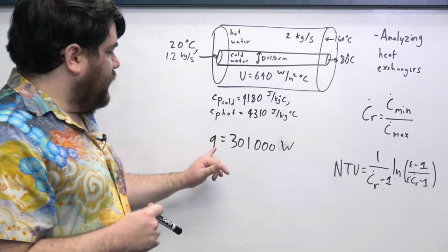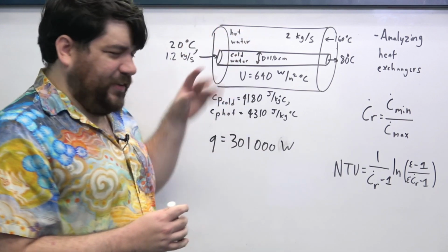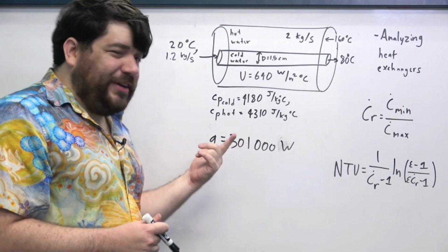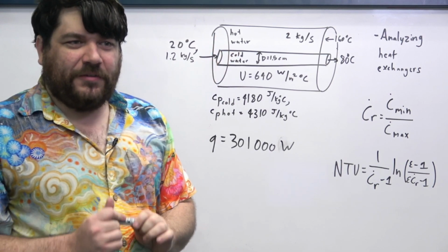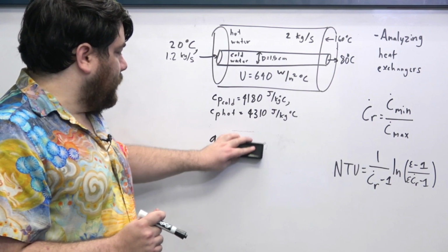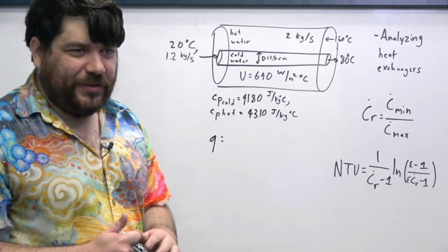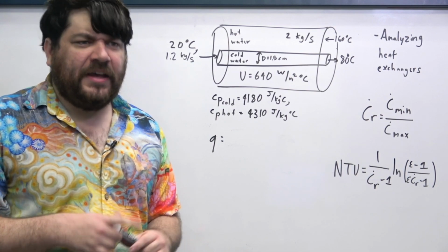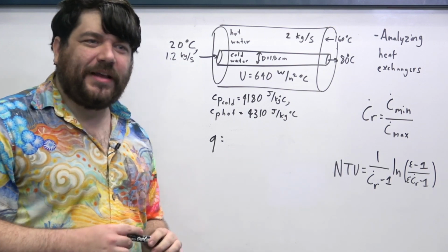Okay, can we use this information to find something else about the state of this heat exchanger? And the answer is yes, because we can use that same golden rule to try to figure out the temperature of the hot liquid at the outlet. Remember that the equation that I wrote down earlier is valid for both the hot liquid and the cold liquid. We have to change the mass flow rates and the specific heat capacities, and we might have to change the order of the temperatures in the delta T, but it nevertheless works.